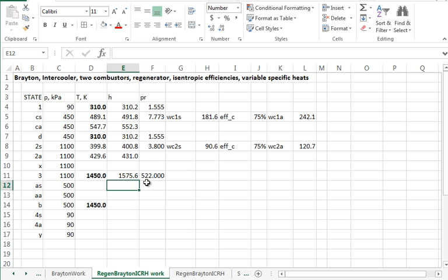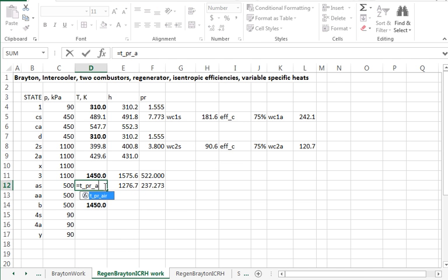Let's just say it. Okay, now, so you take that Pr and multiply by the actual pressure ratio. It drops in pressure, and so the Pr is lower. I use that Pr to get the h. h is a function of Pr for air. Get that Pr, and I get the temperature. Temperature is a function of Pr for air, and there you go.